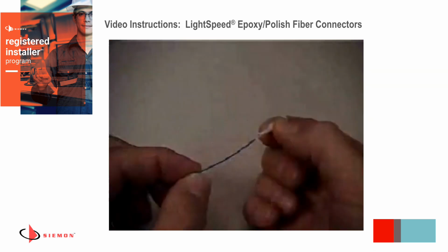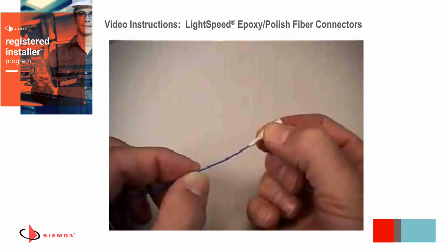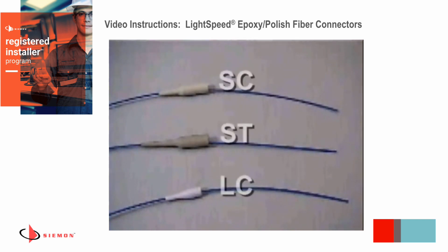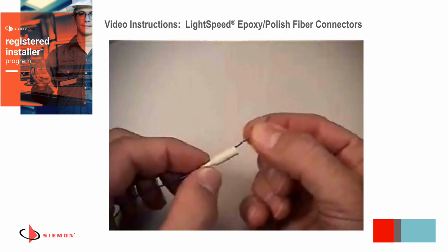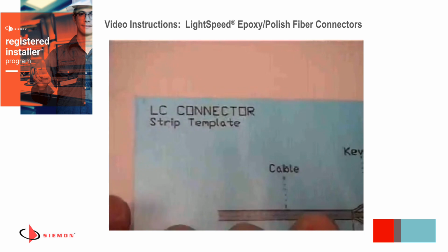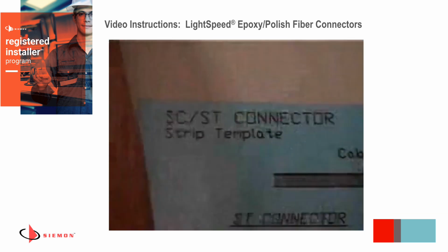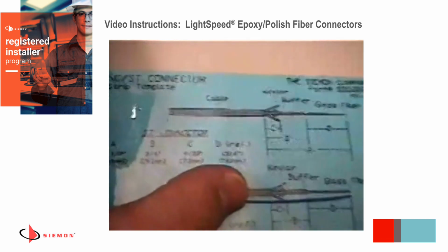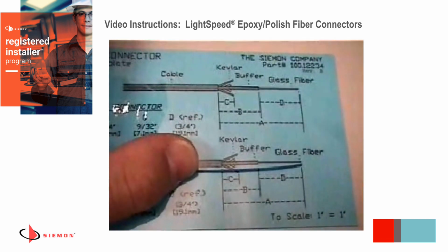After exposing an adequate length of buffered strands from your cable, the first step is to install the strain relief boot. Perhaps one of the most commonly forgotten steps, this can certainly be frustrating if discovered after polishing several connectors to perfection. Slide the 900 micron boot onto the buffered strand, narrow end first, until it is out of the way. Using the template card provided, choose the proper template for the connector being terminated. The LC template is on one side and the SC and ST on the opposite side of the card.